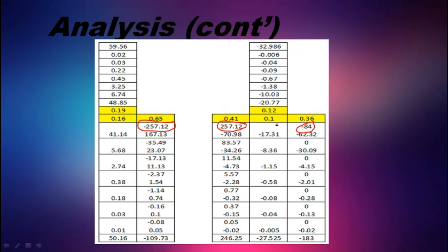If it's positive, it becomes negative. If it's negative, it becomes positive. So since the value that we calculated will be a positive, it'll be negative. That negative value will be multiplied by the corresponding distribution factor of the member. As such, we will get these values. All these values are negative.